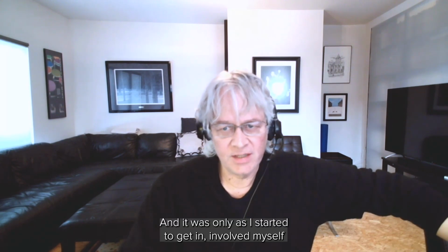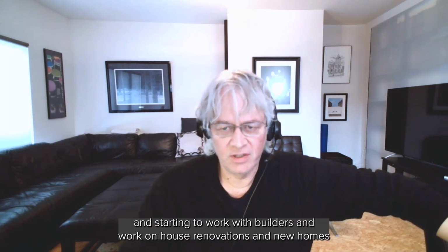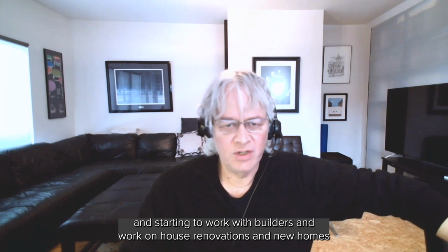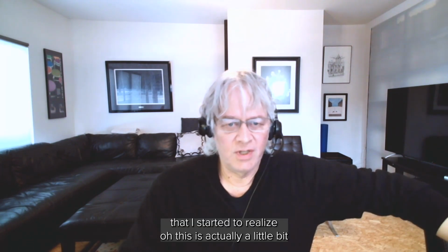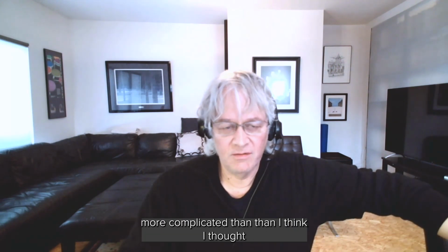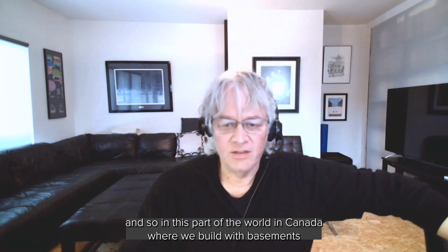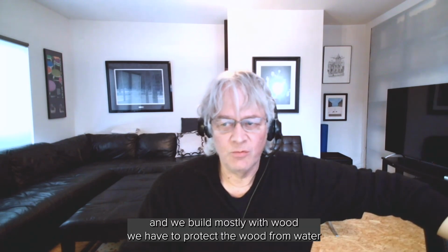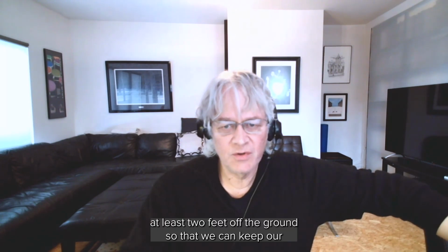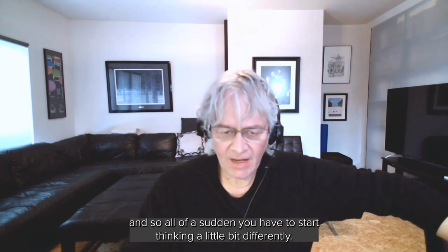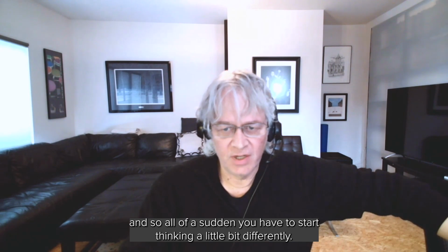And it was only as I started to get involved myself and starting to work with builders and work on house renovations and new homes that I started to realize, oh, this is actually a little bit more complicated than I thought. And so in this part of the world, in Canada, where we build with basements and we build mostly with wood, we have to protect the wood from water. And so that's the reason why we typically build at least 2 feet off the ground, so that we can keep our floor joists away from the ground. And so all of a sudden you have to start thinking a little bit differently.